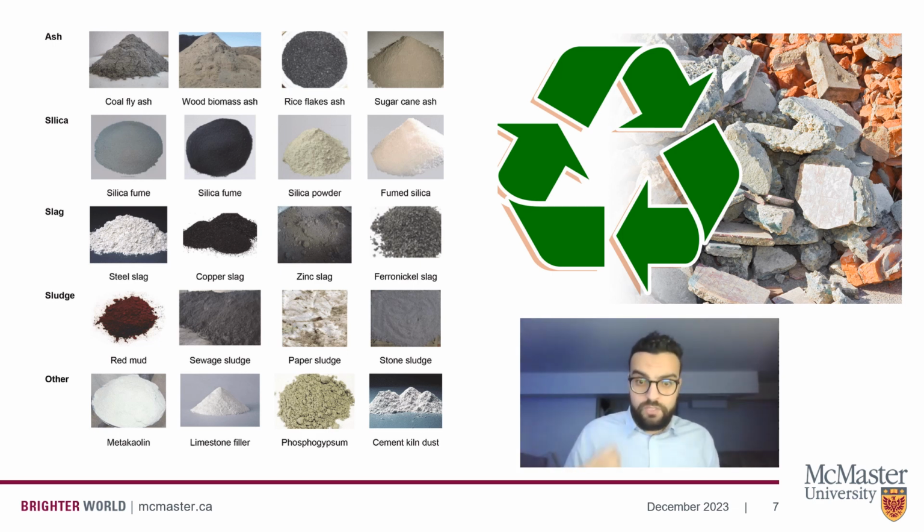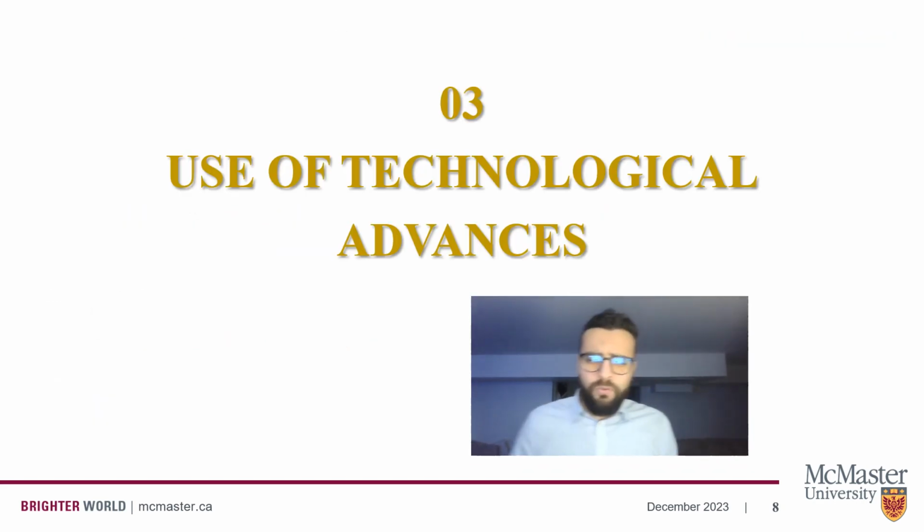You need somebody who has enough experience to go and try, for example, let's say that one day, for a specific reason, for example the humidity of the recycled particles, or the degree of fineness of the supplementary cementitious materials is not as typical as what happened before. So usually people will add more superplasticizers or viscosity modifying admixtures to bring the concrete to a workable state. However, we don't think that this is the right way.